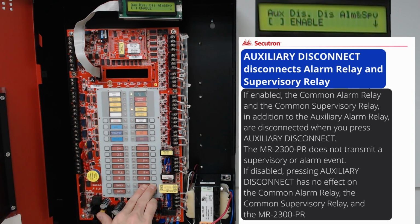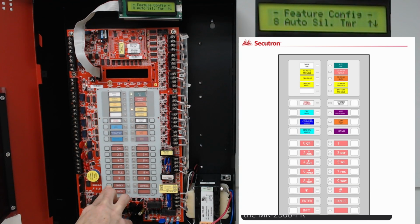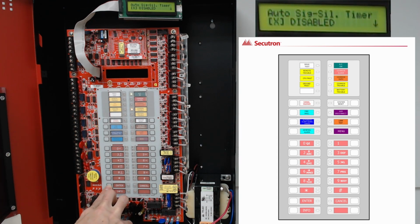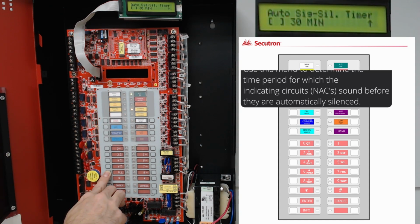By pressing Cancel, we exit back out to the previous menu screen. The next option in Feature Config is Auto Signal Silence Timer. By pressing Enter, we get to see the options for our Auto Signal Silence Timer. By default, Disable has been selected, but we can scroll through to find the other options. We have a 5-minute Auto Signal Silence Timer, 10-minute, 15, 20, and 30-minute options.